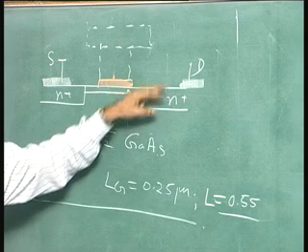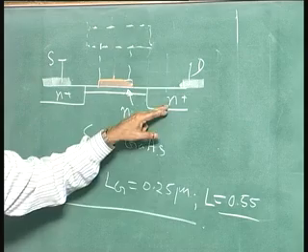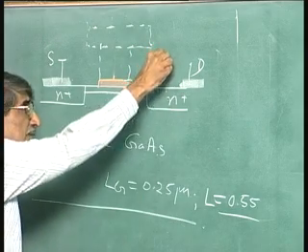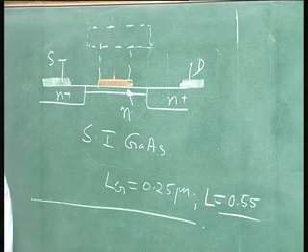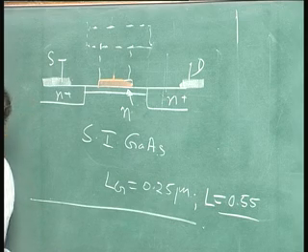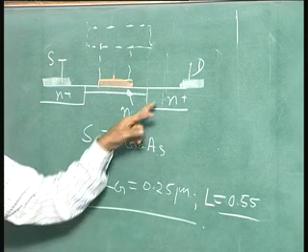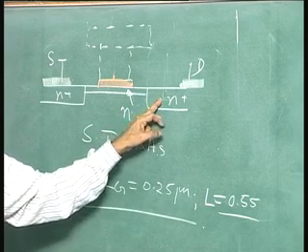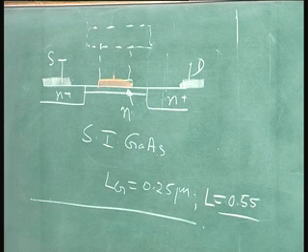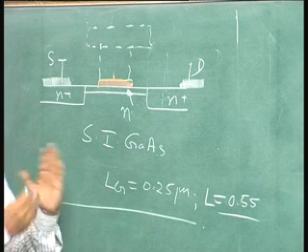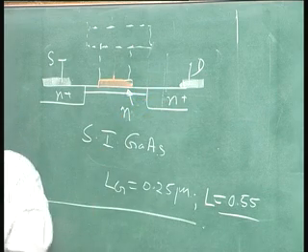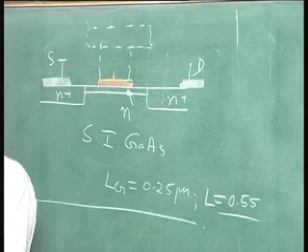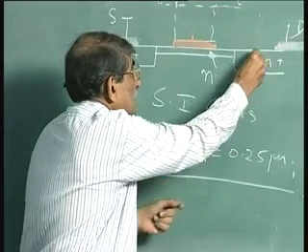So, you have a beam current which decides how many atoms are coming. So, the atom can rest here or there. That is called the straggle, a statistical phenomenon. In the sense, if you take the doping profile here, it goes through a peak, and the peak corresponds to what is known as the projected range. Most of the atoms land there. Similarly, the atom not only has got a right to move in that direction anywhere like that, it also can go like that. It goes here or there.